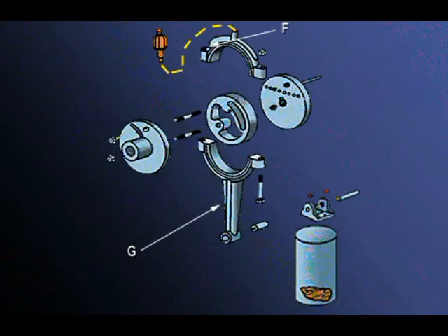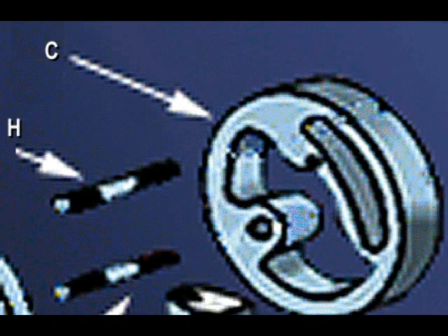Part F is the top of the connecting rod, and it is connected at the bottom at G with bolts and shims, in a way that allows movement between the eccentric and connecting rod assembly. The shaft, flange, and eccentric rotation cause the connecting rod to move up and down. Note the slots in eccentric C. Both the stud at H and the shaft travel in these slots in the eccentric as it rotates.